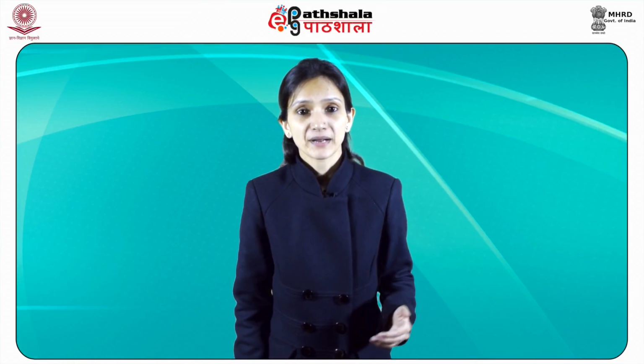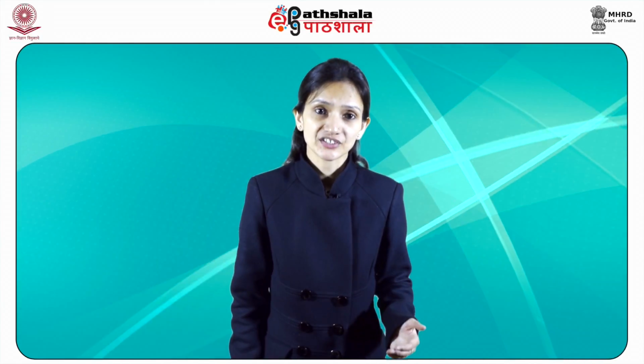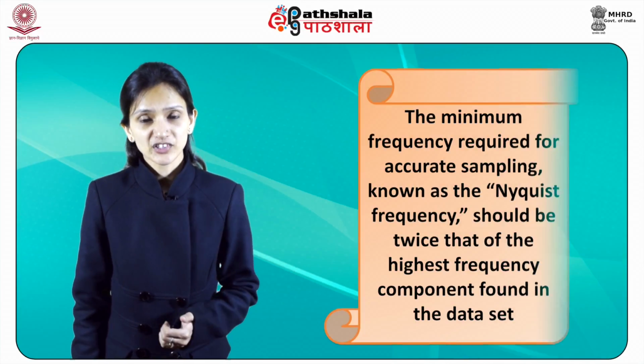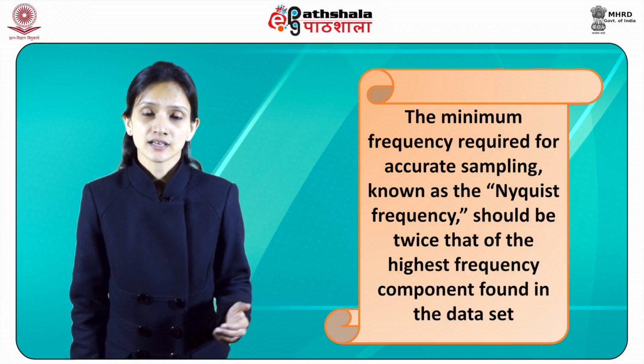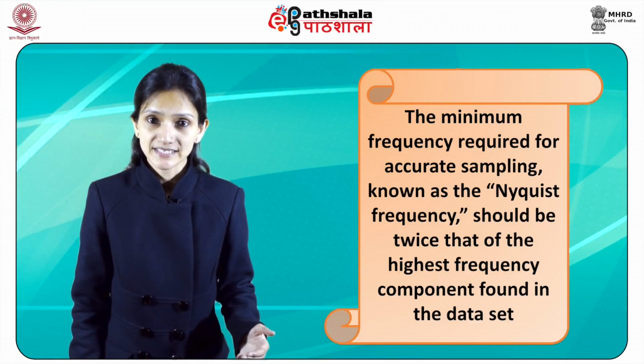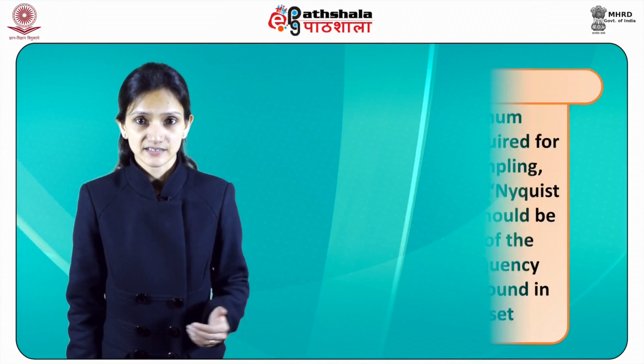The upper limit of resolution is determined by the speed of the computer and the memory available for data storage. The minimum frequency required for accurate sampling, known as the Nyquist frequency, should be twice that of the highest frequency component found in the data set.